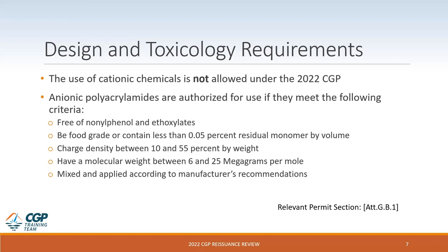And in all circumstances, when these passive treatment chemicals are applied, it's important to ensure that the manufacturer's recommendations are followed, because depending on the chemical, that may change from site to site. And so that communication is important when designing and implementing these passive treatment systems.